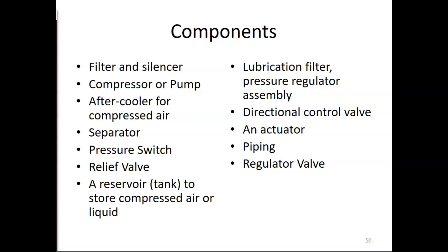Why? Because if you overpressurize hydraulics, you're going to blow your seals, and that's a really hard thing to replace. Think about your car. If you blow the seals on your car, how hard is it to get into every single seal in your car and replace those? You are looking at a lot of shop time and a lot of shop money, and you might as well just replace the vehicle.